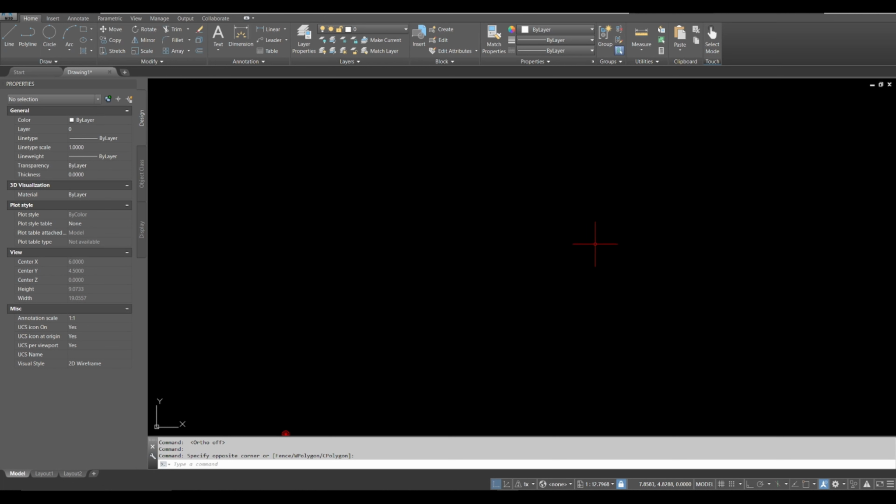So it may not come across well in the video, but you can see if I activate my line command and I spin it around, it's updating fairly frequently. It looks pretty smooth, right? And that's because I have my intelligent update set to 60 frames per second. By default, it's set to 20, which to me looks a little choppy. I have a 144 hertz refresh rate monitor, so it doesn't really look super great for me.